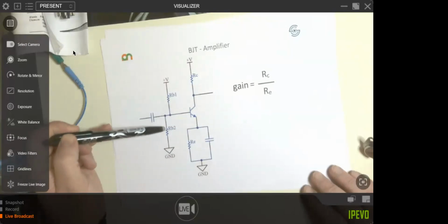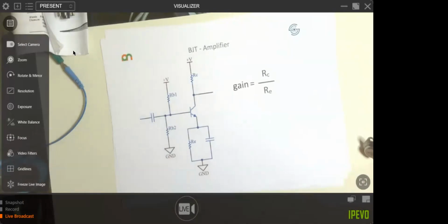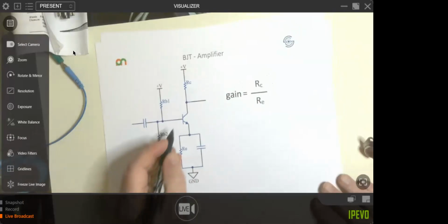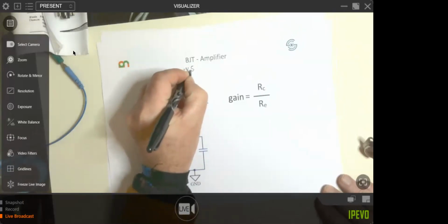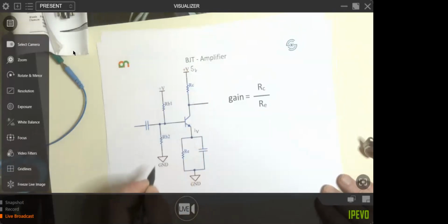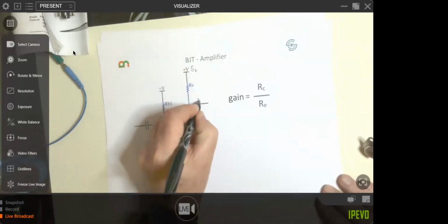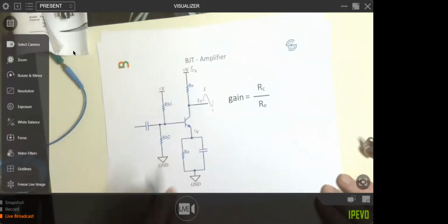And then these two resistors here are for biasing your signal. So what you generally try and do is make that say 5 volts. And if you make that say about 1 volt, which means you'd want that to be about 3 volts. So this could swing up and down from 5 volts to 1 volt, if that makes sense.